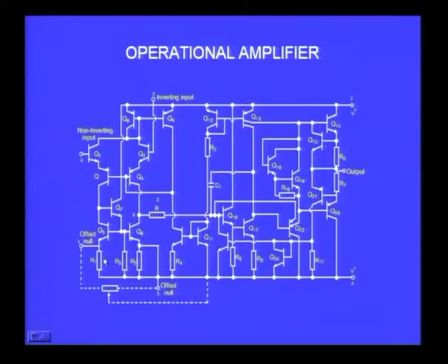And if you look at the resistors, you find there are only up to R11. So you have only about 11 resistors, 20 transistors. You have more transistors than resistors. And do you have any capacitors? Yes, you have only one capacitor at the center, which is actually a compensating capacitor, for frequency compensation. So you have 20 transistors, about 11 resistors and one capacitor. This is in striking contrast to what you normally come across in discrete electronics. In discrete electronics you would have very few active devices, and a larger number of passive devices like resistors and capacitors.